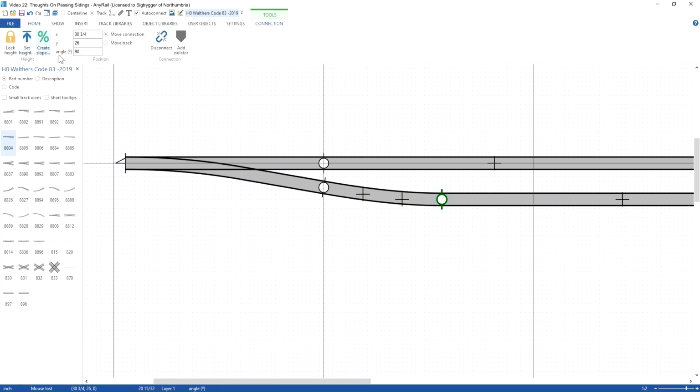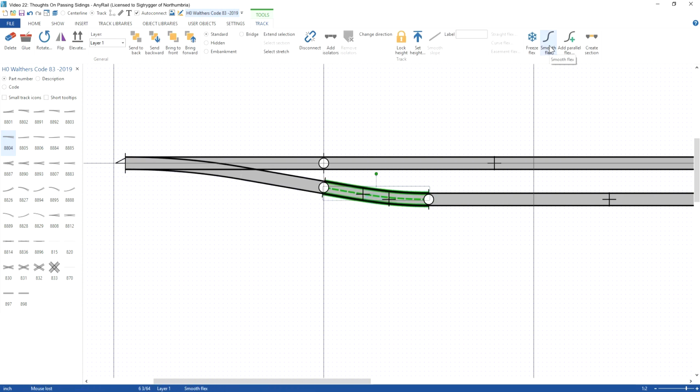Now let's move it the other way. Let's go down to 30 inches. Now remember, this track is 27 and 23/64. So let's go to 30 inches up here. We'll smooth it again. And you'll notice I moved 3/4 of an inch, but I went down to, well, just about a 19-inch radius. So you don't have to move this point very far to get big changes in the radius.